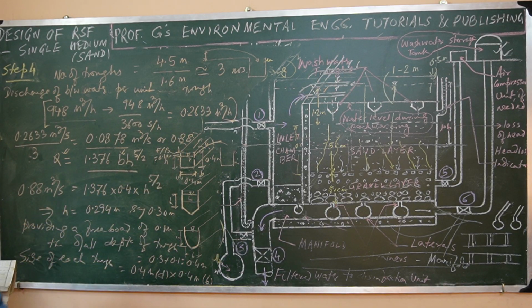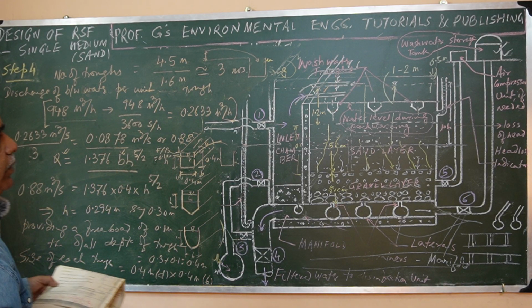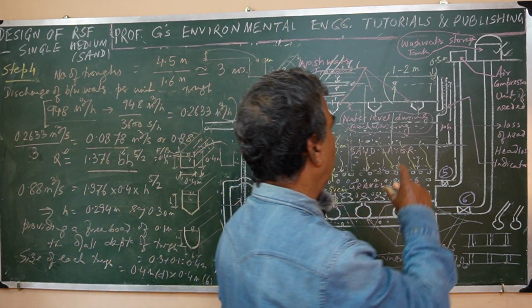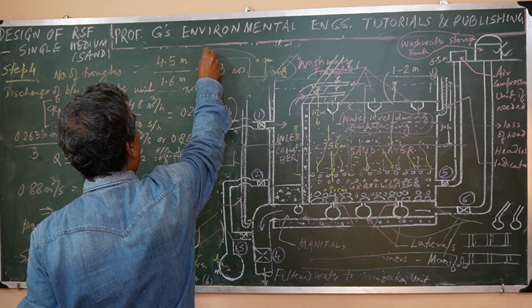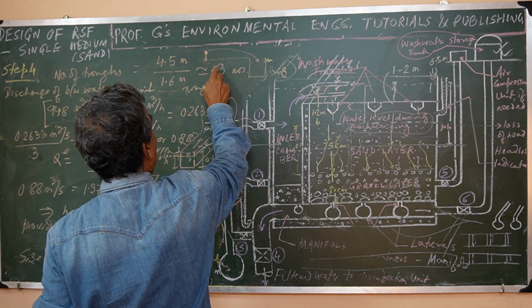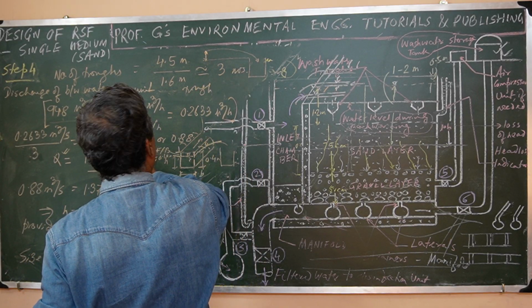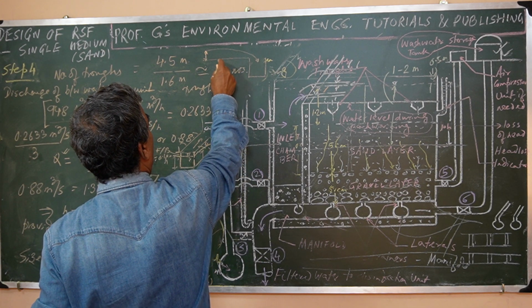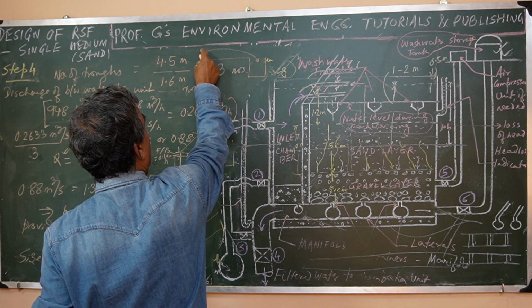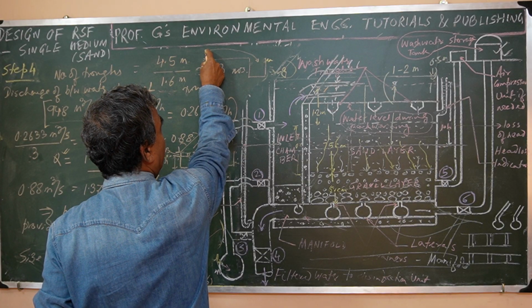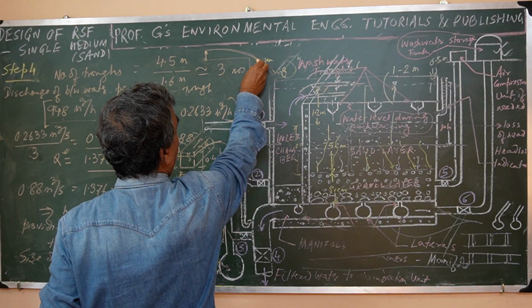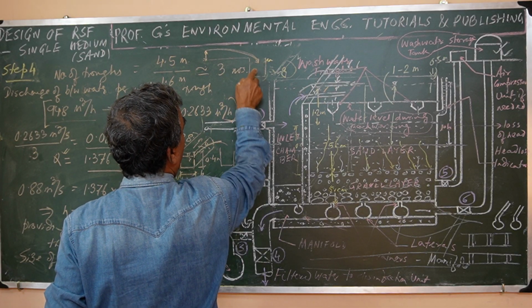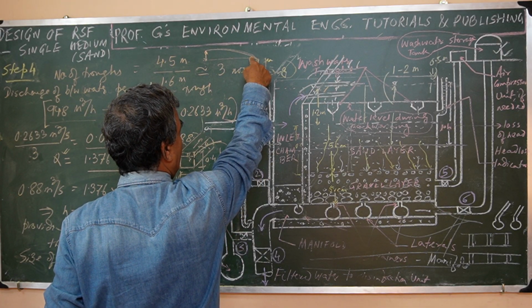So now the dimensioning of that is clear, including the water level in that, and that water level has been determined based on this equation for when the depth will be at the uppermost end also, right? Because this actually will be the backwater curve profile. Before falling into that, this would be a sort of critical depth.